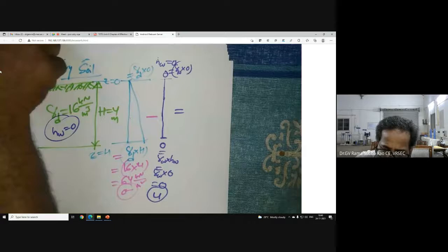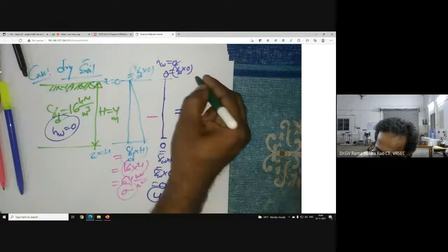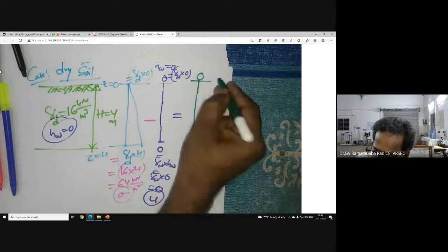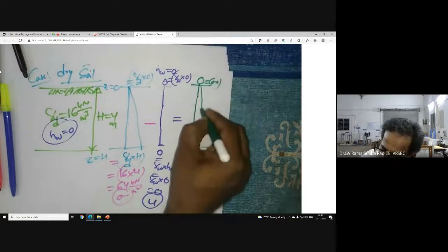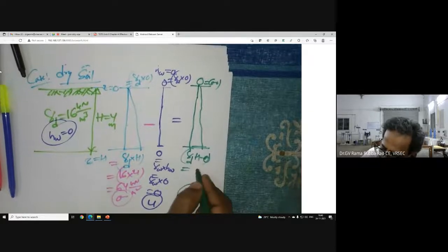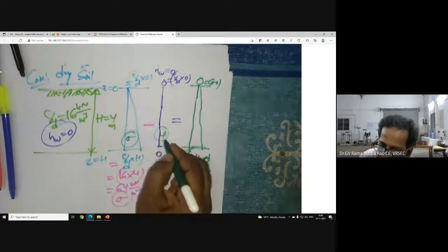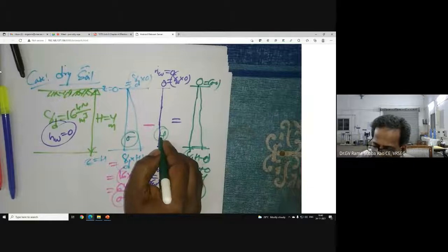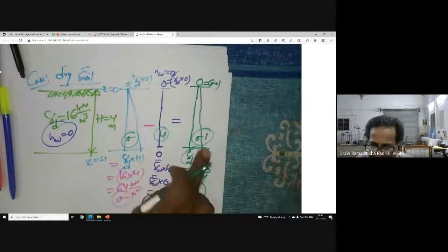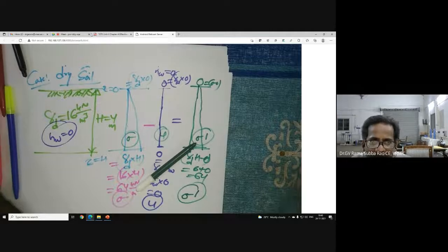But my interest is very clear. I want to draw the effective stress distribution diagram right from top to bottom. 0 here. Why am I writing 0? As you know, 0 minus 0 is 0. Now here at the base, gamma d h minus 0, that we already calculated, 64 minus 0, which is equal to 64. This is the sigma diagram. This is the pore water pressure distribution diagram. Pore water pressure distribution is also called the neutral pressure diagram. Now this is effective stress, which is also called intergranular pressure. This is the original stress acting on the soil mass. Thank you all.